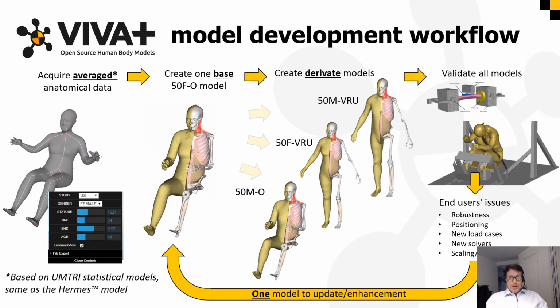From this base model, 3 derivative models are created using mesh morphing by means of a custom morphing script. Additionally, some post-processing is performed to guarantee that the element quality as well as contact definitions match the base model quality. The main difference between a base model and the derivatives is the nodal coordinates.